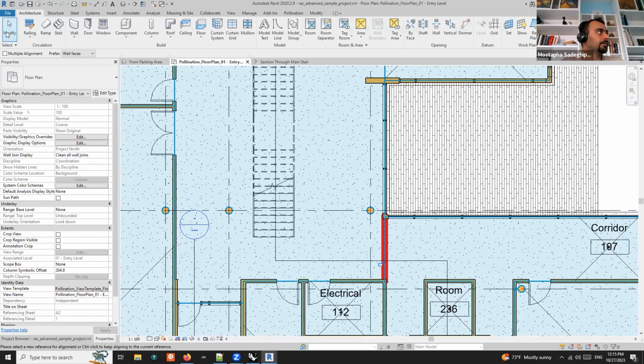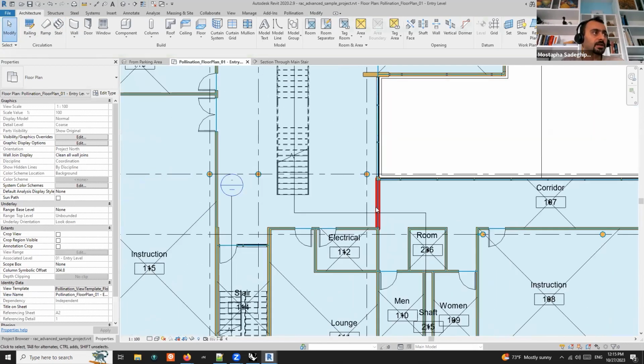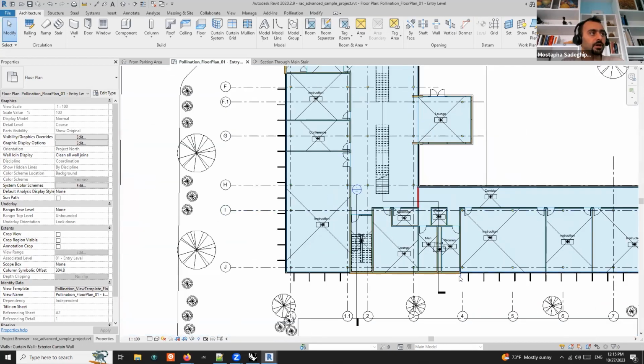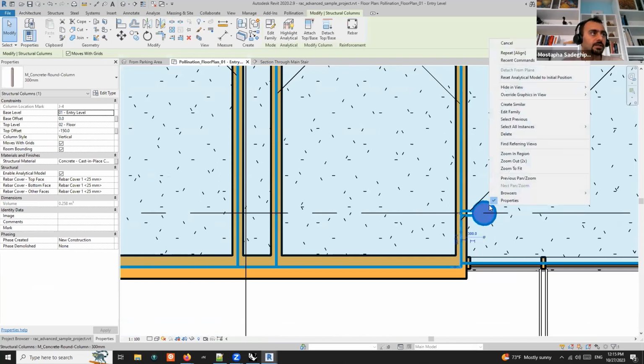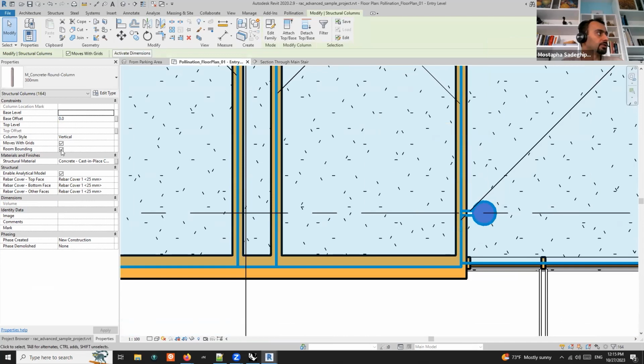So again, I can fix it inside Revit. And option 3 is just to use the one that we talked about, right? Instead of trying to do remove short segment, just select all this, select all instances in the entire project, and make sure they're not room bounding.